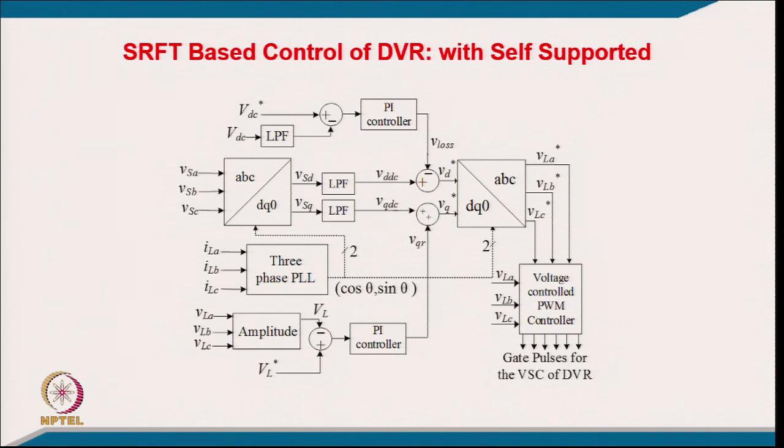Apart from that, the injections will be of voltage preferably at 90 degrees, because it should need the reactive power only. So, here of course, with this voltage source converter we have a reference voltage and a feedback voltage. As I told you, here also you might have some ripple, even the second harmonic wave voltage unbalance, which has to be compensated. So, this low pass filter is required to get the DC component. Then we have a PI control.